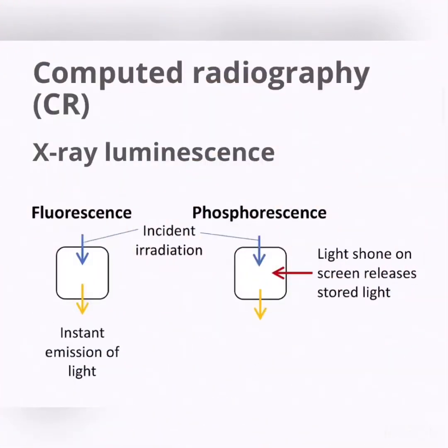Computed radiography is a digital replacement of conventional X-ray film radiography and offers enormous advantages for inspection tasks. The use of consumables is virtually eliminated and the time to produce an image is drastically shortened. In computed radiography, when imaging plates are exposed to X-ray or gamma rays, the energy of the incoming radiation is stored in a special phosphor layer.